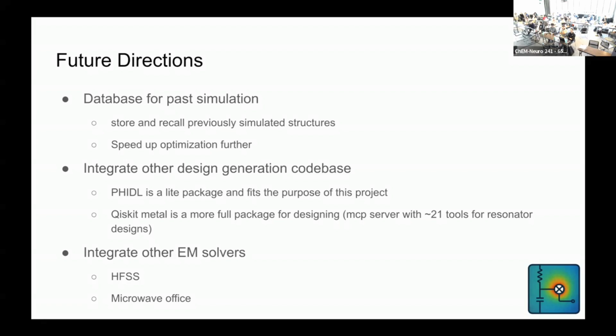One could imagine a more complex version of this problem that could be done with the same strategy, which is maybe build a resonator with a Purcell filter and some loaded admittance at the end, which could represent your qubit. In that situation, you could generate the structure, have Sonnet or your solver of choice analyze the admittance of each of your components and optimize each of your component parameters to get you the Purcell filter tuning that you want.